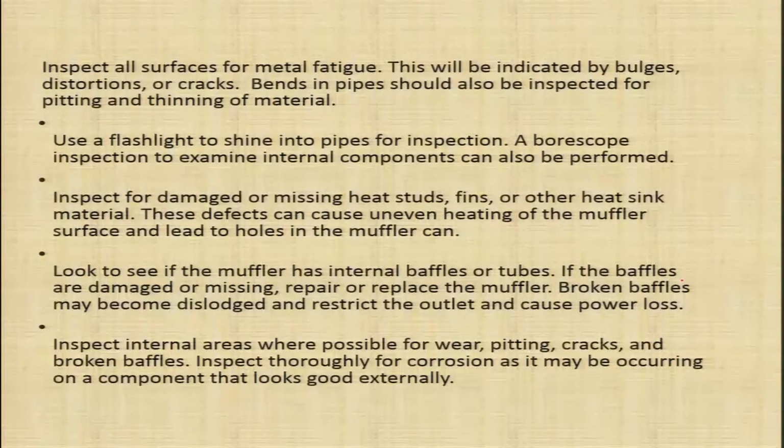Inspect all surfaces for metal fatigue. So, the complete system, all the surfaces, should be checked for metal fatigue. This will be indicated by bulges, distortions or cracks. So, metal fatigue will be indicated by cracks, by bulges or distortions on the surface.